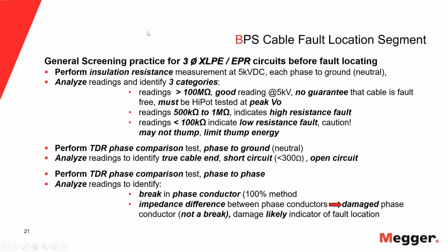Many of these distribution cables are 50 ohm cables. So if you suddenly had a spot where you only have 10 ohms, you would see a downward blip. If you suddenly have a spot where you have maybe 150 ohms, you have an upward reflection. You still see the end of the cable, however. That is important, okay? So why do we do this?